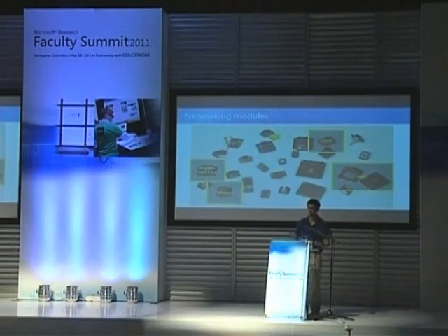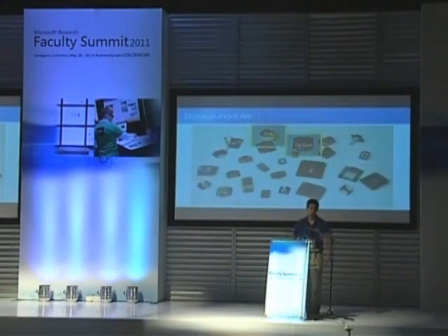Then there are communication modules. You can hook this up to Wi-Fi or Ethernet, or if you're building a sensor network, you can add an XBee, a Zigbee low-power wireless mesh radio module. Also serial line, if you are connecting this to a PC for data logging, for example. Storage modules: the SD card, USB host. It's quite powerful. You can plug things like a keyboard or a mouse into this tiny computer via USB, and it'll work.